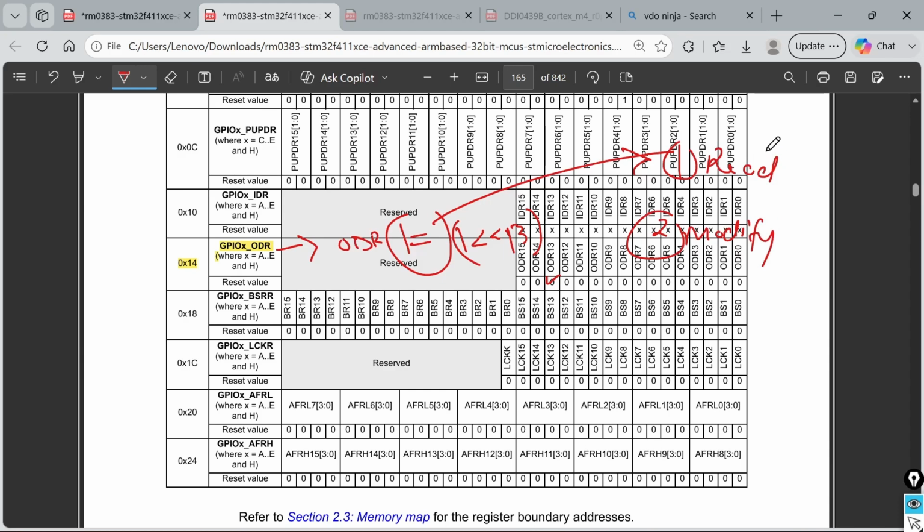It will read that value, store it in a local register, modify that local register, and then store the value back in the RAM, wherever the address is. So you see there are three steps here.